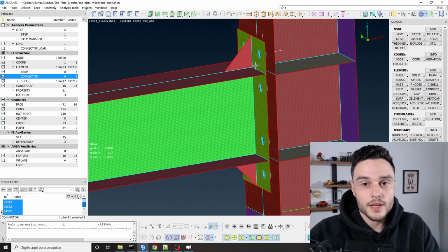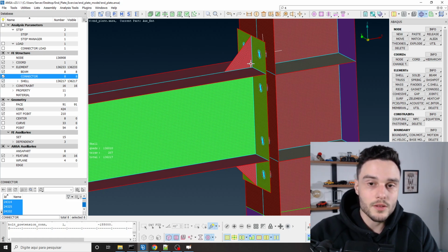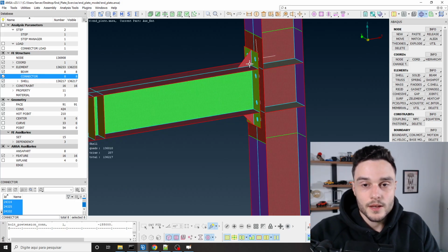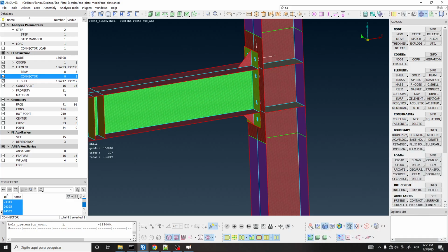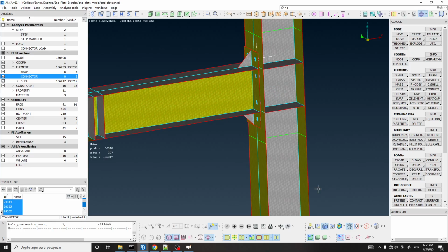So we are going to create a surface to surface contact. The first thing that I need to create is the set. I need to create one set with one surface and another set with another surface. Before we create the set, in the draw mode, this button here that controls the draw mode, let's select this option here, int. When we select this option, we are able to see the positive side of the faces or of the elements and the negative side of the elements.